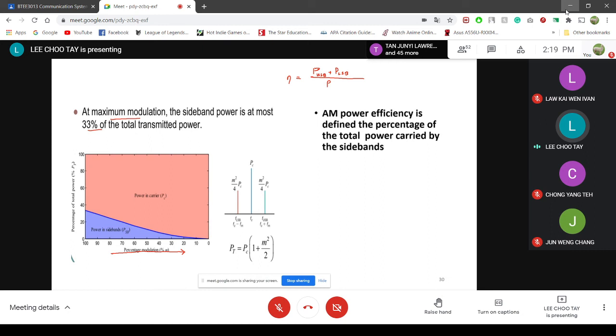Let's go back to his problem. His method is to address the problem with selective filtering. With selective filtering, we're going to have problems designing our filter, especially when our upper sideband and lower sideband are so close to each other. So how do we do a sharp cutoff? You want an upper sideband, you want a lower sideband. It's very difficult to do a sharp cutoff, especially when you have a significant amount of power at low frequency. So if your spectrum has significant power at low frequency, it's very difficult.